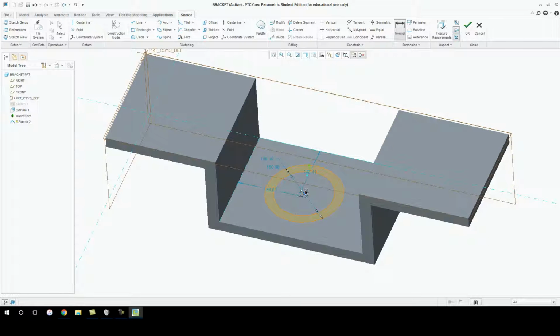So let's go ahead and do the dimensioning option, and the total width of this is 300, so this will be centered at 150, and the distance across here is 375. So half of 375, or I can just type 375 divided by 2, which will put that in there for me as well.